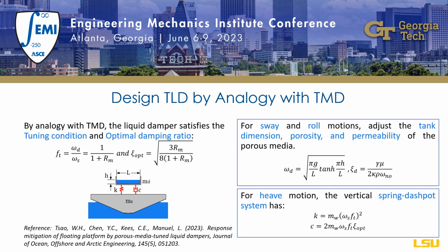And before the simulation, we have to design the tuned liquid damper properly. In traditional tuned mass damper design theory, two core requirements should be satisfied: the tuning condition and the optimal damping ratio. They are usually related to the mass ratio.